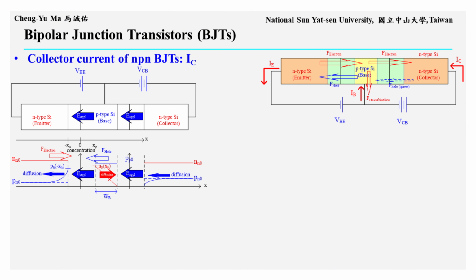We first start from the collector current, IC. As mentioned earlier, IC mainly comes from carriers injected from the emitter into the base, then diffusing across the base and being collected by the collector. Therefore, IC is essentially a diffusion current in the base region. Since diffusion current is determined by the concentration gradient of the diffusing carriers, we first need to find that concentration